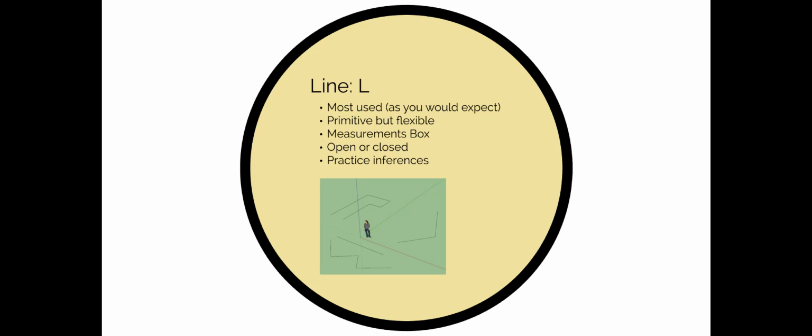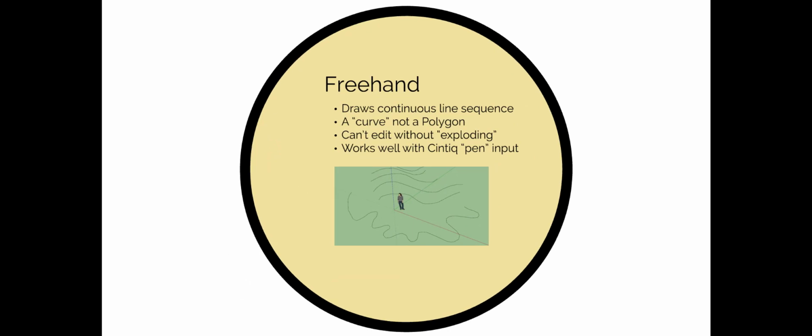The line tool, most primitive, but totally flexible. You can use open or closed lines. You can practice inferences drawing that to keep the lines parallel to one another or perpendicular. And we can use the measurements box to actually input specific dimensions if we want to.